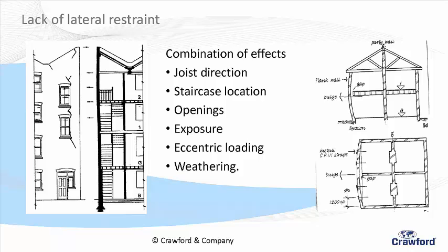Lack of lateral restraint, and that's pretty much as it says on the tin. Over there you've got a semi-detached. Can you see the wall is just bowing on section? And on plan it's bowing as well. And that is what it is. All walls on a building want to move out. They never want to move in, because inside you've got